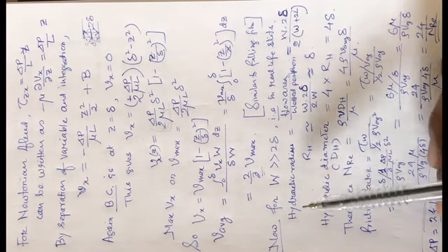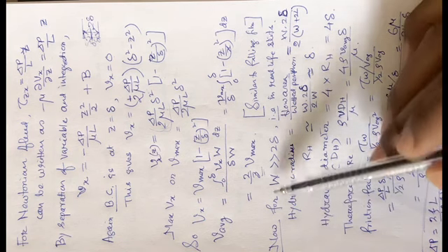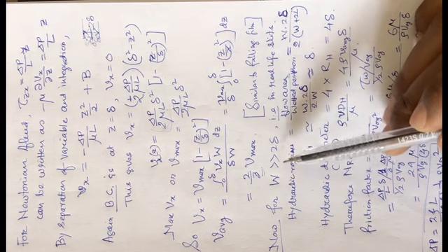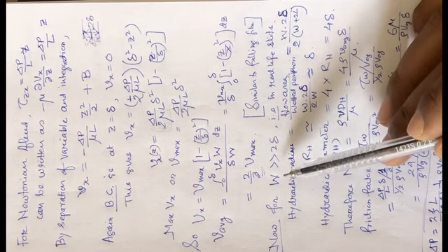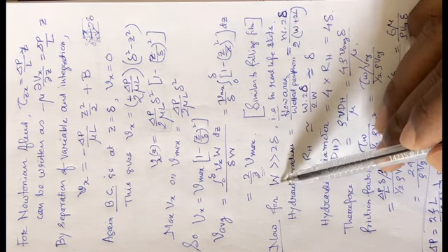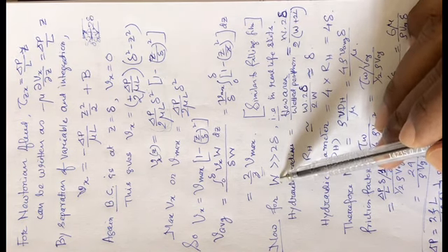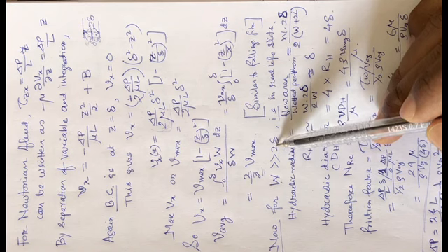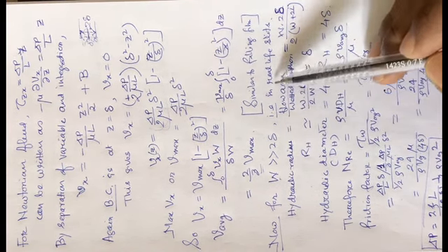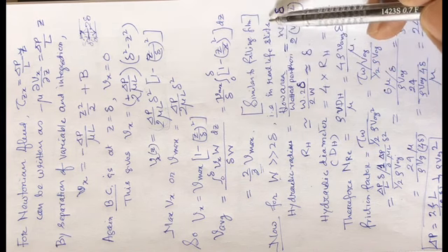Now one interesting thing happens. What about the Reynolds number? Okay, here is the condition for slit flow. We have used the term slit flow. Slit means actually a small opening between two walls. So the width of the wall, W, is quite great as compared to the gap between the two plates. So that is the real slit.